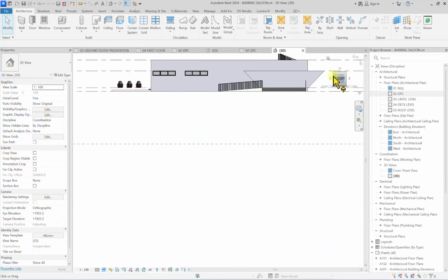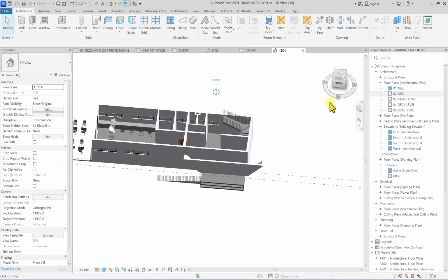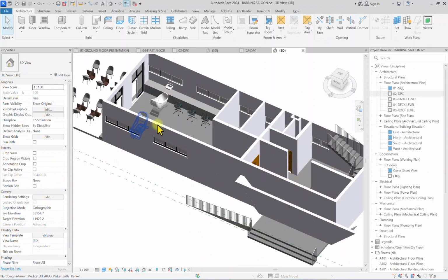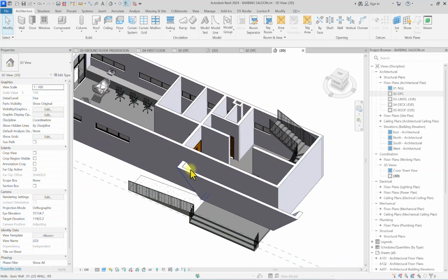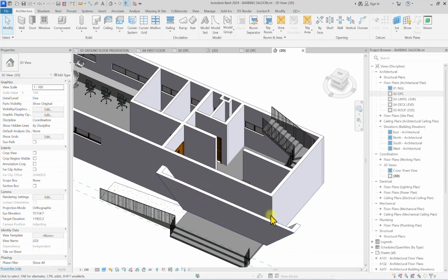So after this is done, we'll now go to 3D view and see what it's looking like. So as you can see this thing now, I want to create kind of like a cube effect, a slanted cube effect on this facade. So with this now, I'm now going to drag you into roofing now. So roofing in Revit is very simple. So what roofing involves is that you just pick a plane where you want to roof from and draw your roof. So for instance, I want to draw a roof to over this point in this project.